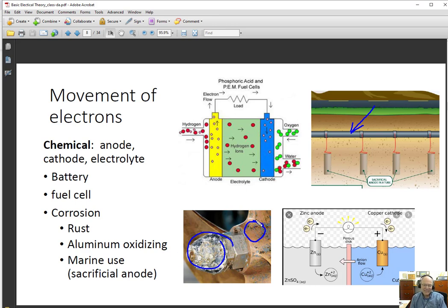It doesn't hurt the bronze to have an excess of electrons, but it does hurt the zinc to lose them over time because it changes the atomic structure of the zinc, i.e. it basically disintegrates. Now, over here you've got a schematic, and there's zinc and there's copper. All it is showing you is that electrons are flowing out of the zinc into the copper, and as a result the zinc deteriorates, the copper does not.